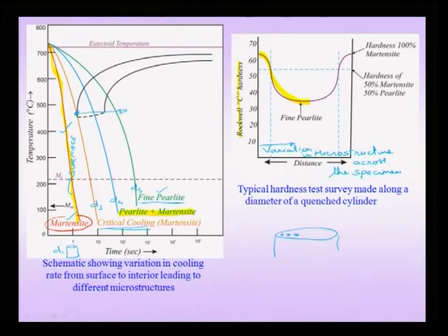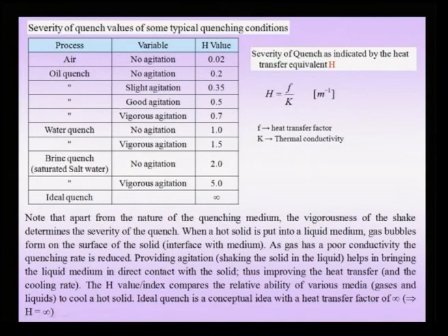Then such a material will be easily hardenable, hardenability being the ability to harden with the least severe quench. So, I will repeat again that hardenability is a technical term. It is the ability to harden a material by producing martensite via the least possible severe quench, and that is one benefit of moving the TTT diagrams to the right, and that can be done via alloying, as I pointed out, but additionally also the thermal stresses produced in the material are going to be low.